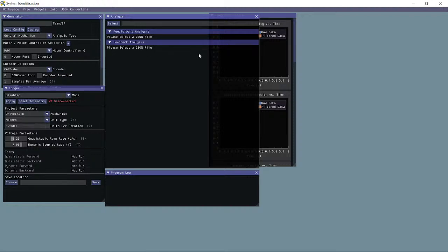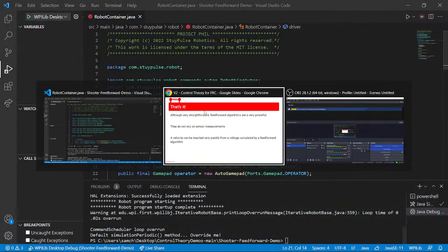Feed forward is generally good enough. If you notice issues where the speed is not able to get back up, like in this game, shooting 2 balls pretty rapidly, cycles really quick, if you notice that second ball is not following the same trajectory, that's when you might need a PID because there's unexpected error from the first ball leaving the shooter. It just couldn't spin as fast. So technically those constants changed. That was unaccounted for though. So when the second ball goes out, spinning at a speed that you might not expect, if that is a noticeable issue, then that's when you might want to put in the extra effort to put some extra measure on it. And that extra measure I will cover right now.